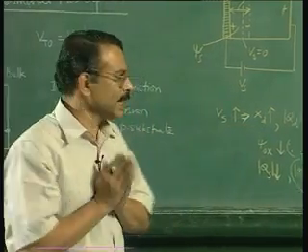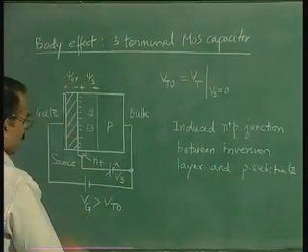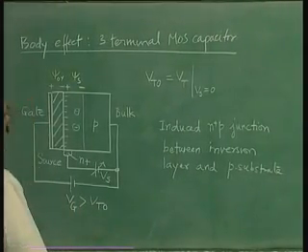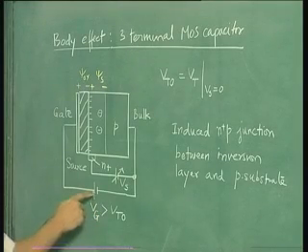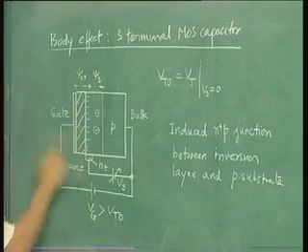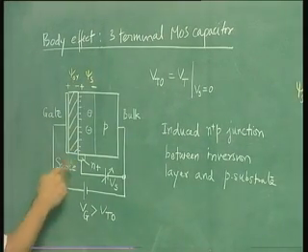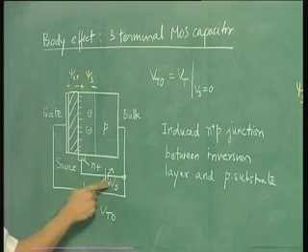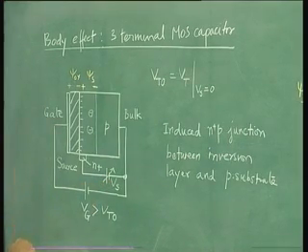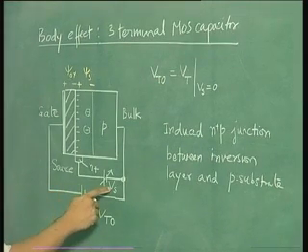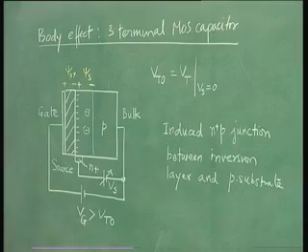So what this means is that we started with a gate voltage which is more than threshold voltage at Vs corresponding to 0, but maintaining Vg at this value, as you increased Vs, you came to a condition when the Qi became 0 for some Vs, which means now this gate voltage which was more than Vt0 is actually a threshold condition for some non-zero value of Vs. Let us see what is this value of Vs, okay, at which the Qi will become 0.